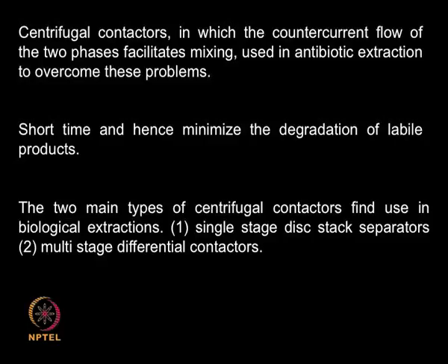Just like the solid liquid centrifuge, where we have a stack of discs placed in the middle near the shaft, you can also have a stack of discs here, but it will be a single stage. Another approach is having multiple stages of centrifuge. That means you will have more than one set of centrifuges for separating out the two distinct layers of the liquids.